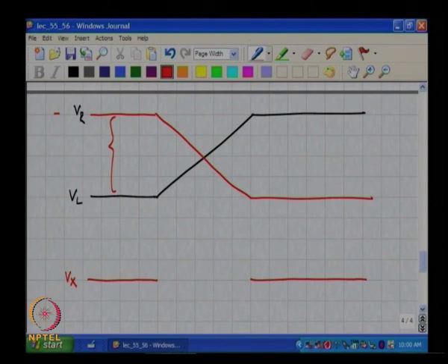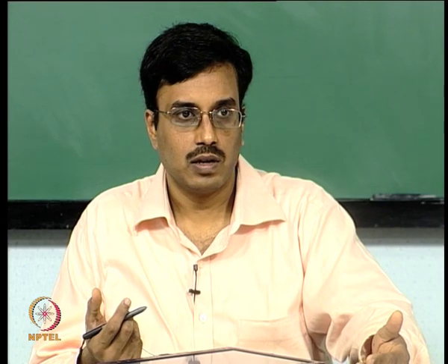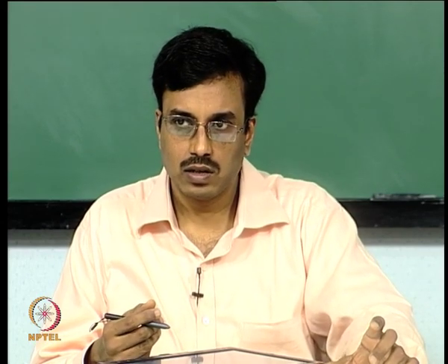Can you comment on the difference between Vr and Vl in relation to delta V? What is the idea behind having a large difference between Vr and Vl? You want to make sure that the current completely switches to one side, which means that the difference between Vr and Vl must be at least delta V. In practice it will be several times larger.